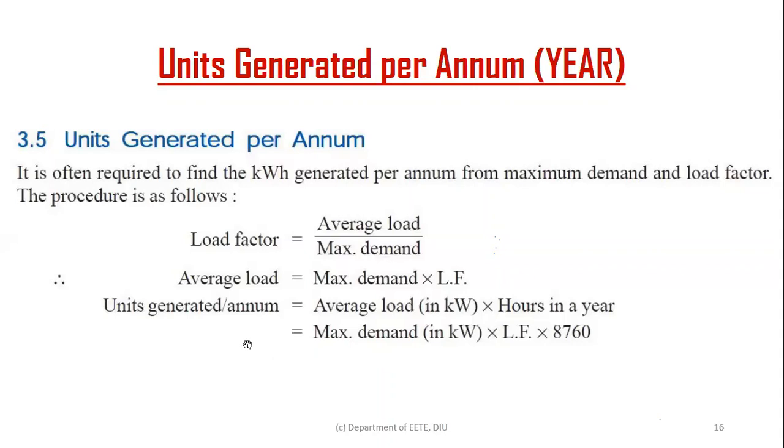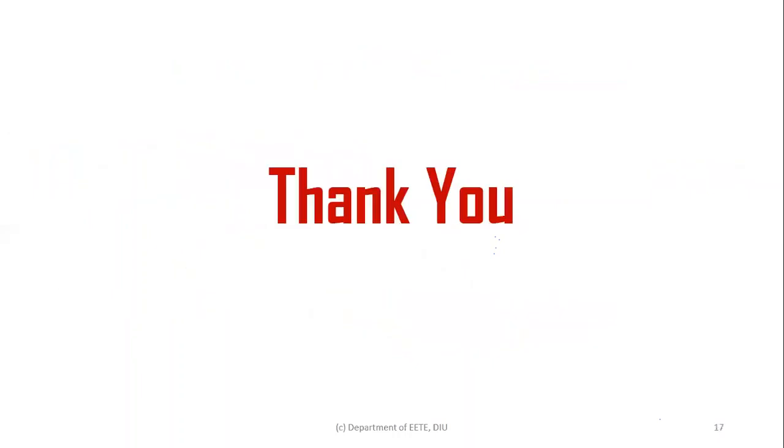So you will just use this equation: units generated per year equals the maximum demand, the load factor, and the total hours in a year. The total hours in a year is 8760. Okay, so that was probably the thing I have right now for the first class.